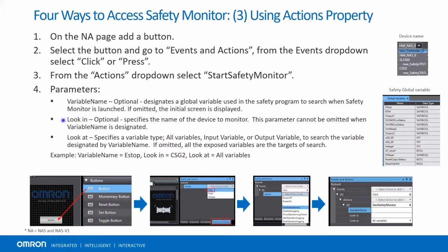LookIn is also optional. Specify the name of the device to monitor. This parameter cannot be omitted when variable name is designated. So the device monitor name is in your Sysmac Studio project.